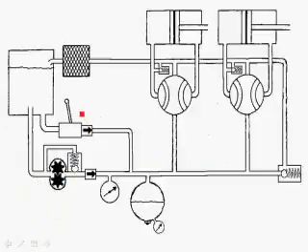So here's our standby pump. I already told you what that was. On big aircraft like this that have a dedicated engine-driven pump and flight controls that are powered by hydraulics, this is going to be electric. It's not going to be manually operated. But on smaller airplanes, for instance a Cessna 182RG, a retractable-gear 182, the standby pump is a hand-operated pump, and you actually have to move it back and forth by hand.